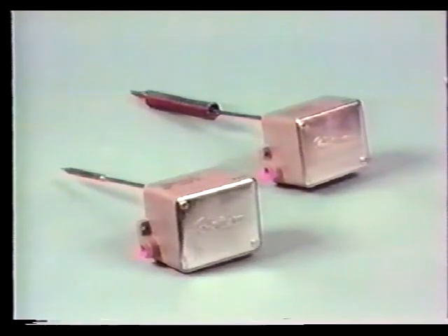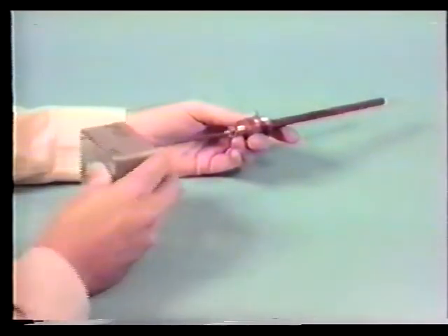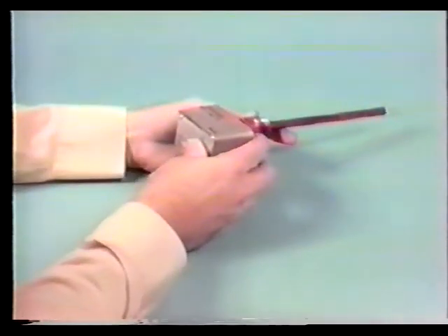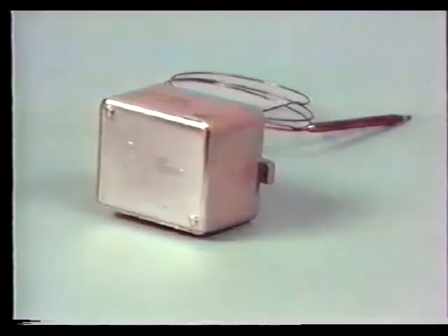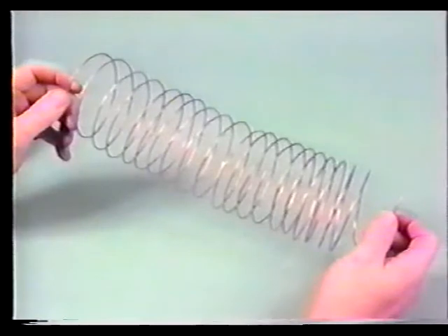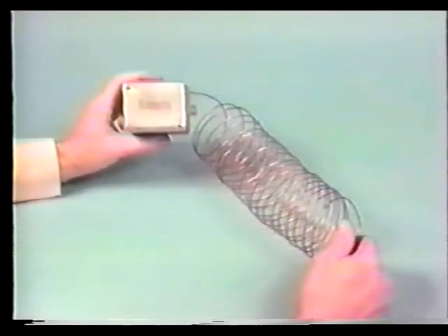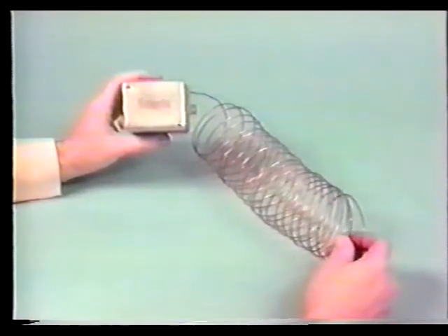Rigid elements and rigid coiled elements are used for air duct sensing generally. However, the rigid element may also be used in an insertion well for sensing liquid temperature in piping. The bulb and capillary styles are used for sensing outdoor air temperature or where transmitter mounting is a problem and a remote sensing bulb is needed. Averaging elements are among the element styles used to measure temperatures in large ducts where stratification of the airflow may occur.